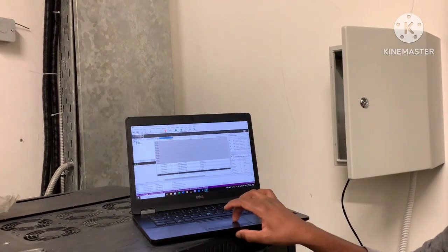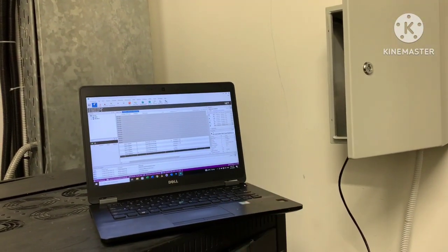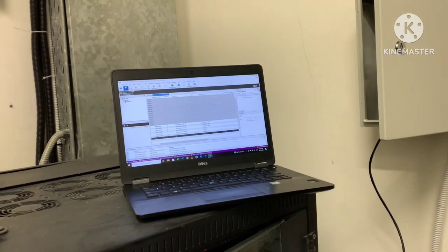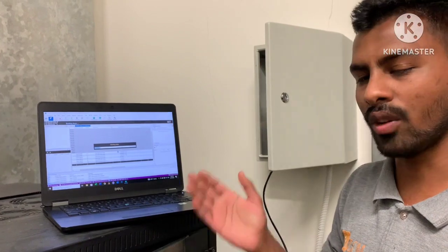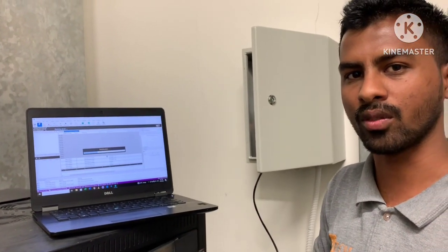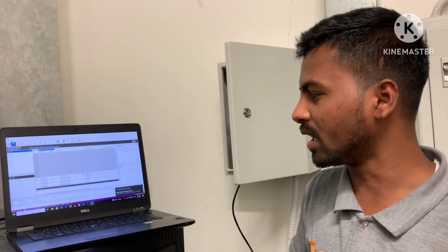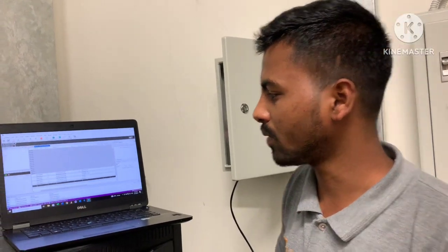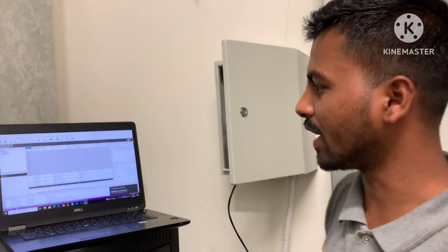Once you make it true, you have to restart the server again, so that whatever changes you made in your program, it will save the changes and restart again. Once this restarts, you will see that I don't need to read the values myself. The BMS automatically polls the meters and reads the value from the meter itself. So let the system restart again.